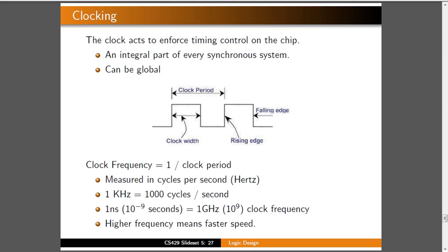One is known as the starting bit and another one is known as the ending bit, or the stop bit. If I say start, then there is a stop bit. So the most general term used is start bit. If the start bit is 0, then the stop bit is 1. It is mandatory to use the start bit as 0 and the stop bit as 1. So A transfers the data using the start and stop bit, and it goes to B.